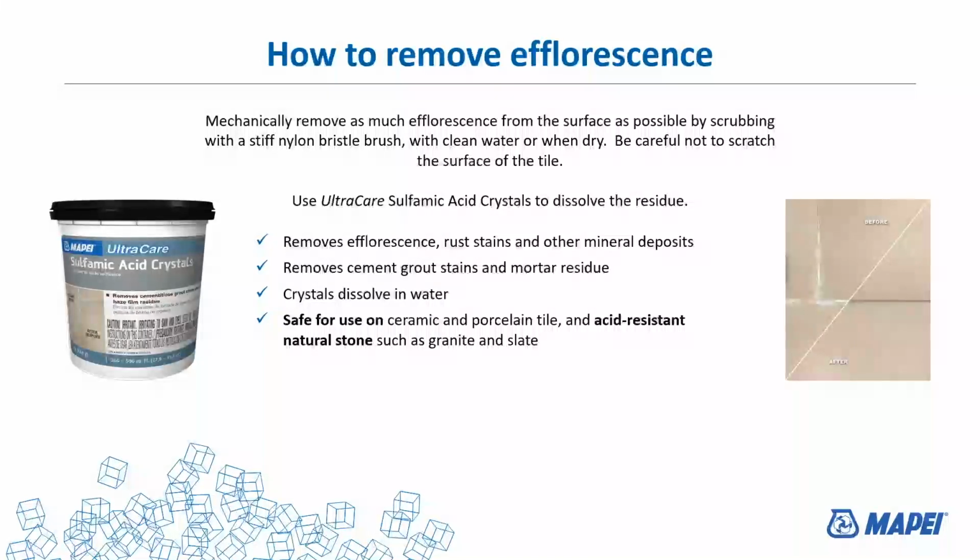It's safe for all ceramic and porcelain tile and any of the acid-resistant natural stones, such as granite and most of the slates. Acids can't be used on things like marble. So if you've got efflorescence on marble, there certainly could be a challenge as far as that goes. The sulfamic acid is a very good product for removing efflorescence off the surface of tile, stone, and grout.